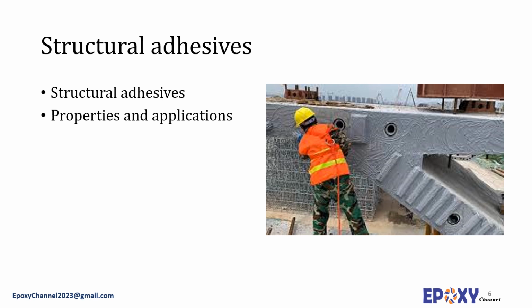These types of adhesives can be used under moist conditions and are employed for bonding hardened concrete to either hardened concrete or wet concrete substrates. However, to provide a good bond in the concrete, the water level must be below 5 weight %.